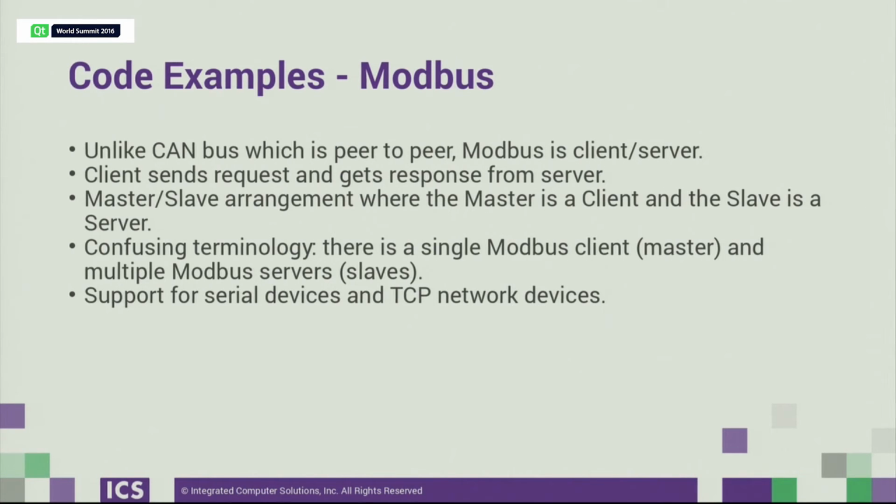So moving on to Modbus. It's somewhat similar, except rather than being peer-to-peer, there's a concept of servers and clients, so you need to keep that in mind. The client sends the requests and gets responses back from servers. The terminology can be a little bit confusing because there's a single client and multiple servers. Sometimes they're called masters and slaves.